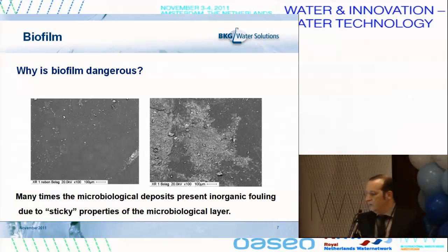Here is a microscope picture of these deposits, and here is what I explained before. This is beneath the deposits, so it was without deposits, and on the right you can see that this was all inorganic. So after drying of the module, what stayed on the membrane was the inorganic deposits attracted by the biofilm in the system. So it has a kind of sticky property, this biofilm.